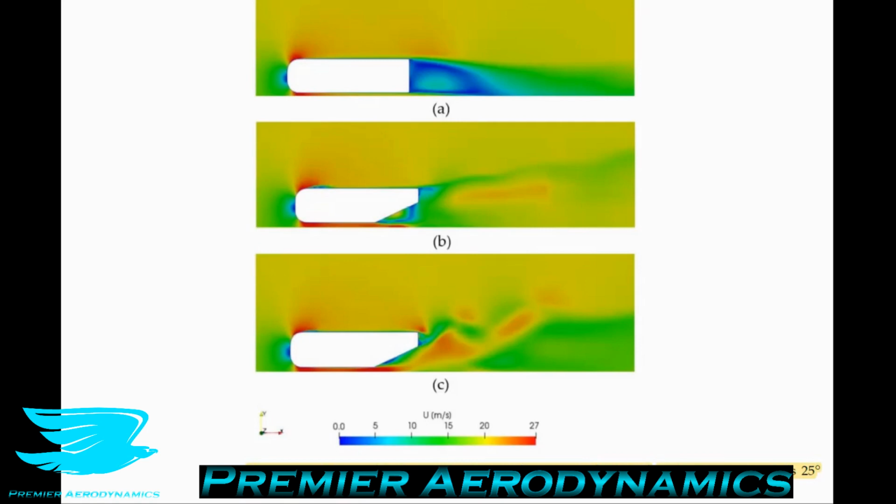For the armored body without any diffuser, there is a massive wake behind. It's just a block going through the air, and as you'd expect, there is a big wake. It's very, very bad. As you introduce this 25-degree diffuser, the wake becomes much better. There's only a little bit of a recirculation zone, but there's almost no wake compared to the original armored body.